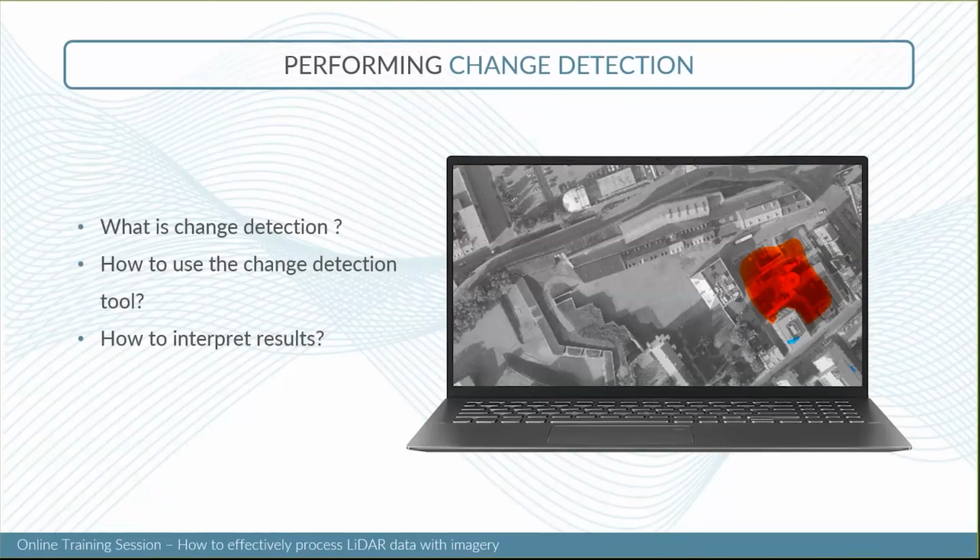You'll subtract your LiDAR DTM from your photogrammetry DSM, and then you'll be able to compare and see the changes in your vegetation growth for analysis. This is one element that could be used for change detection.